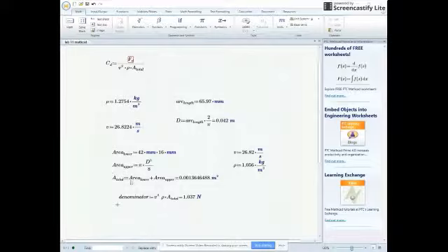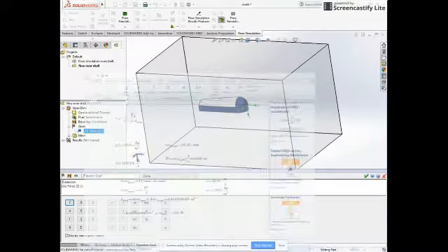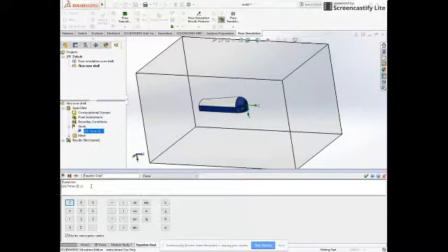It's based on a few different things. The projected area, which is the area seen on the front of the drone. We've also got the velocity again, and the density. That's at 5,000 feet, which is where this drone is expected to perform. So we got the denominator set up with that value for that equation. We're going to plug it in over here, multiply by 2, and divide by that denominator.